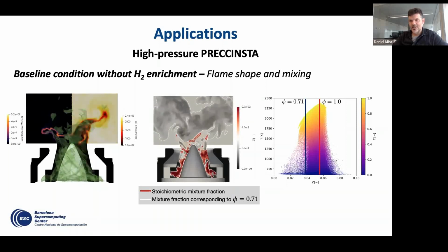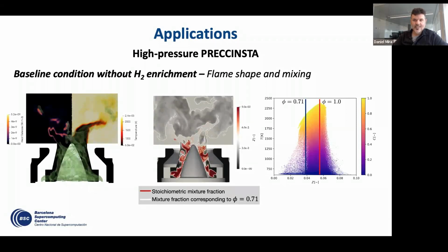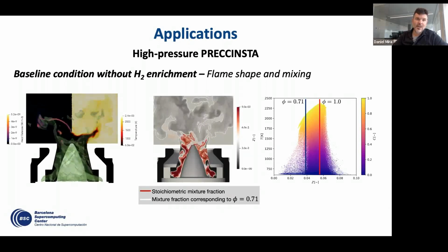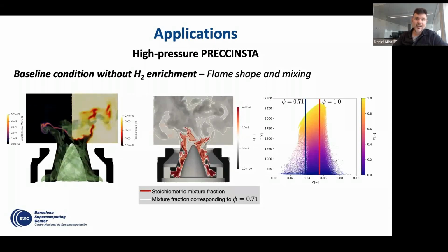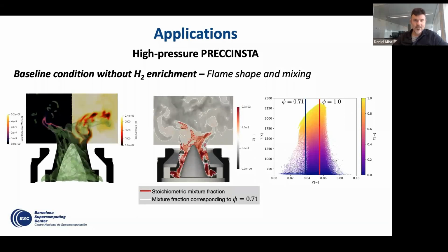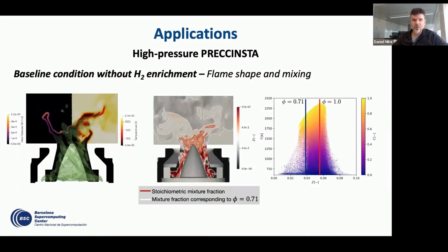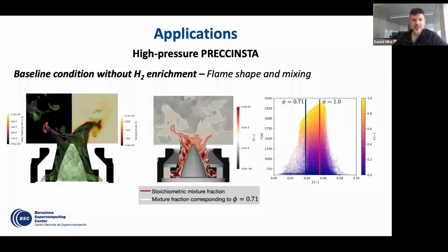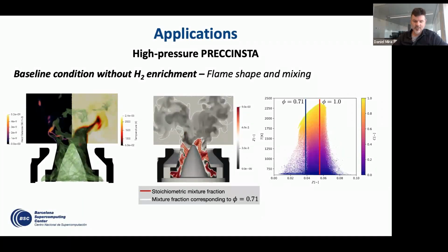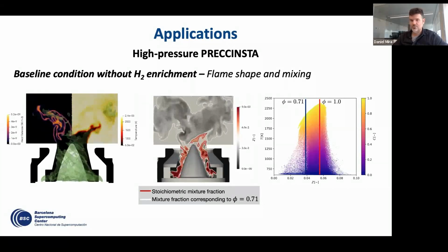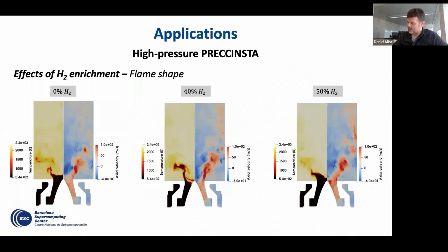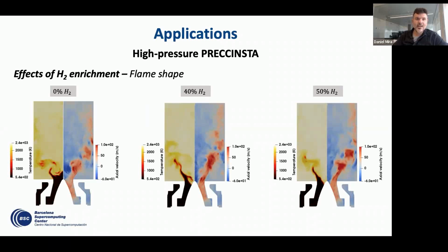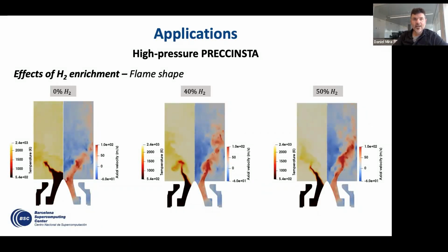And in our case, the central part of the burning is shifted more toward the rich side, which could explain why the peak velocities are slightly overestimated. Of course, this is part of our effort at the moment, to try to predict a better mixing and to understand if this is the mechanism of this deviation. But considering the different limitations and the different possibilities of flamelet tabulation for this kind of flames, we have started to look into the different hydrogen enrichment.